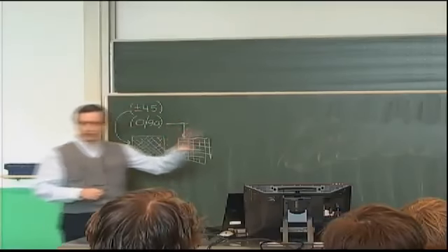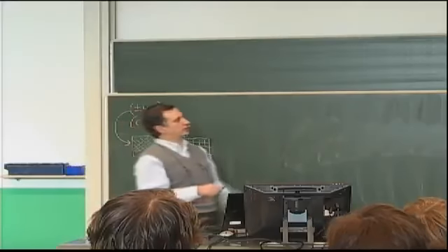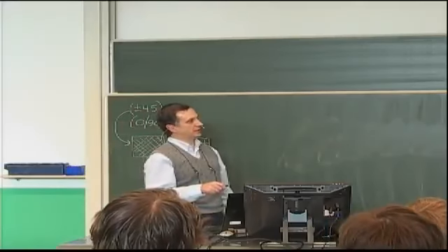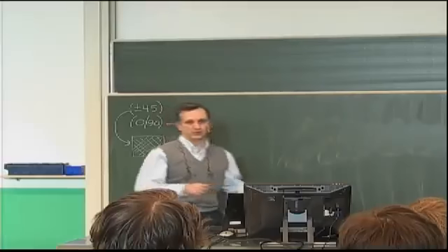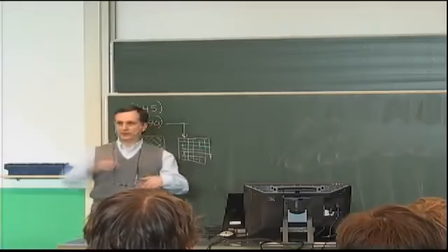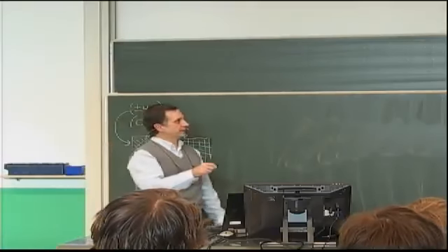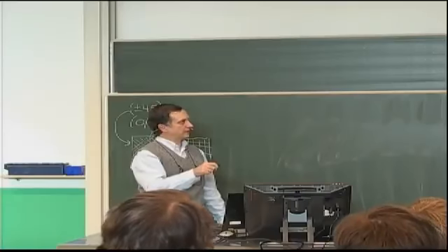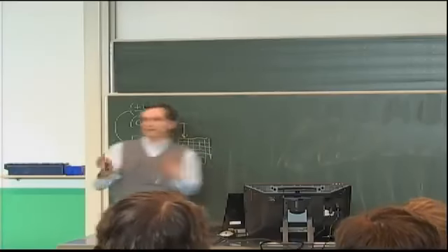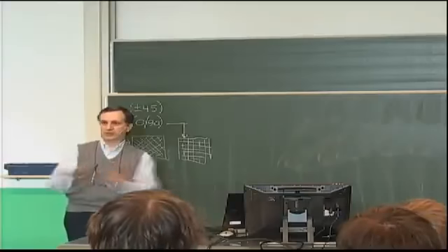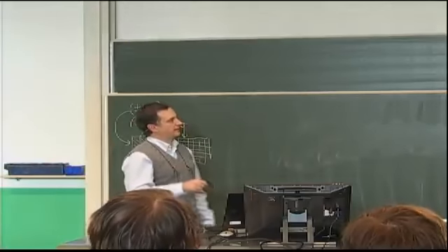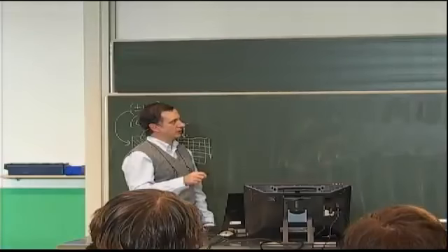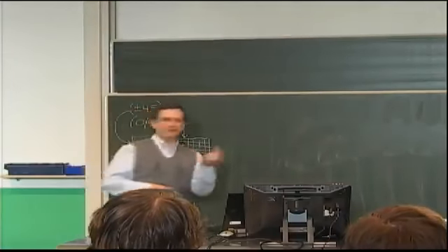So obviously, as you are trying to evaluate the size, you would not just do one location. Location x over a here is 0.005. You would have to check at 2 or 3 locations, starting from the top here of the laminate with a low applied load, to see indeed that there is no location where the stress is wider. Typically you would expect from intuition, and that's what you would find in results, that only really close to the load application will you have the biggest values for the needed reinforcement.